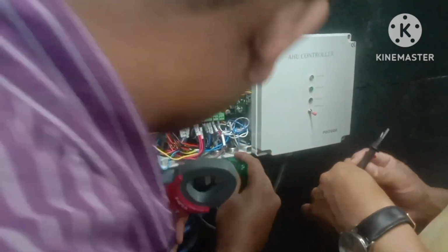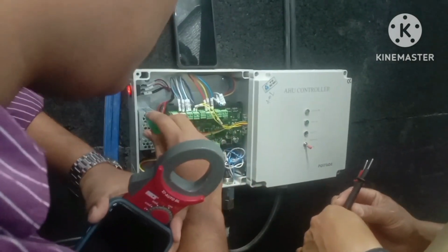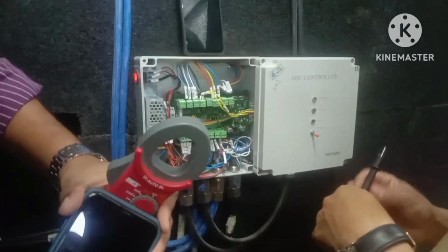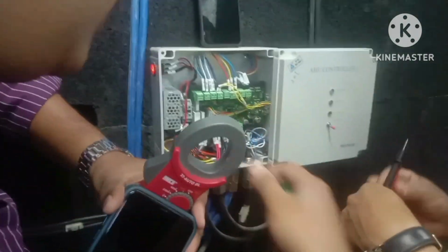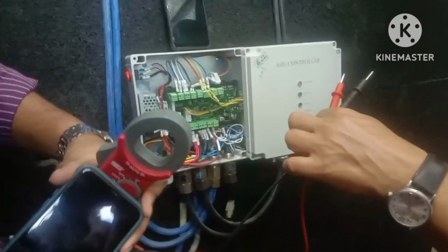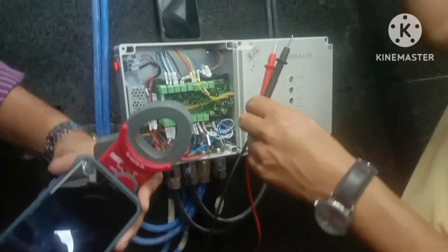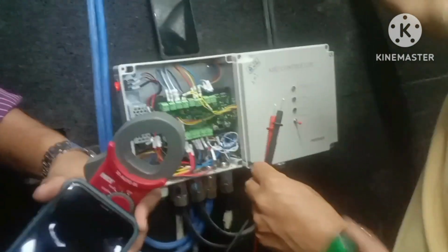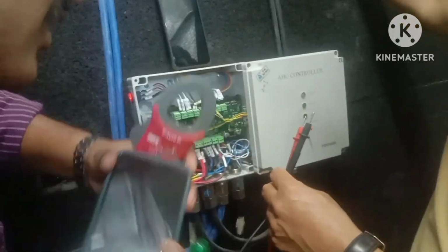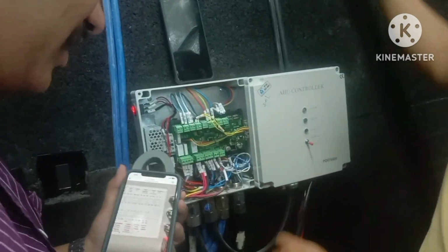And now if you don't get the 24 volt here, at that time you have to remove this SMPS and check whether it is sending 24 volt or not. Take the SMPS to the BMS room, make the connection and check the outgoing voltage, whether the 24 volt is going out or not, or whether the SMPS has blown out. At this condition you will be able to see what the issue is. Now please plug in the wire again.